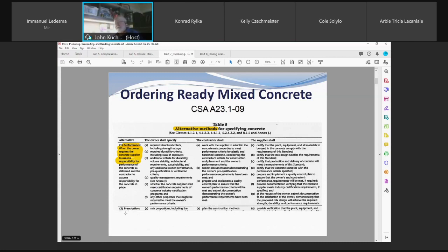And that's where the mix design statement comes in that we looked at, the City of Winnipeg. They want 32 MPa. They want 5 to 8%, okay? It's a class C2 exposure. That is what the mix has to meet. How the contractor/supplier designs and delivers, that's their responsibility. That's a performance. You want strength, you want durability, you want air, and so forth.